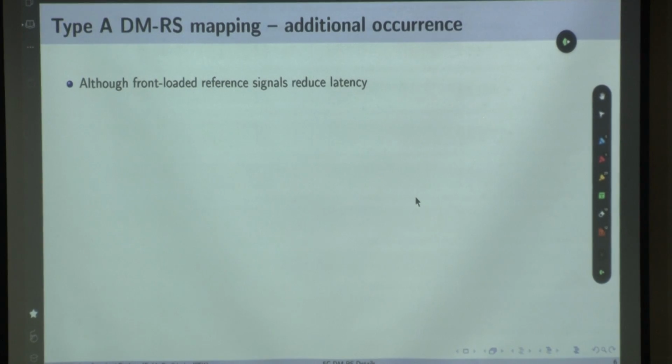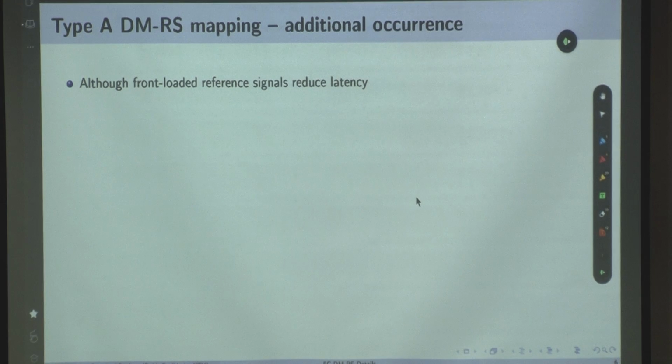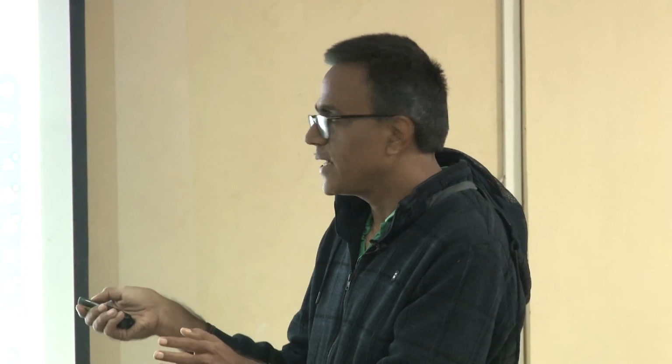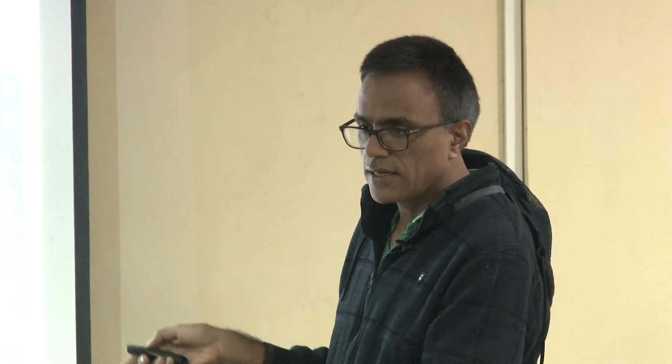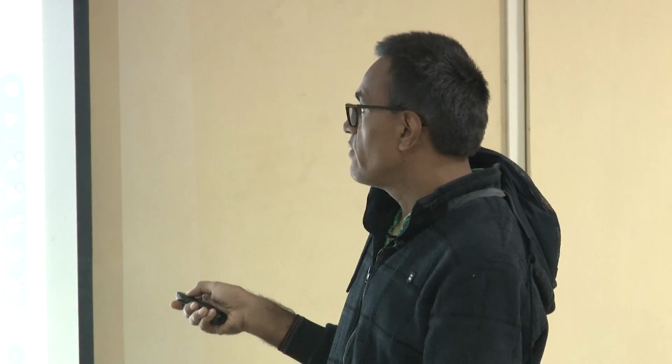Now, although these front loaded reference signals reduce the latency, since they come in the beginning of the PDSCH transmission, whether it was a single symbol or double symbol, and we know the objective is to reduce the latency, they may not be sufficiently dense in the time domain in the case of rapid channel variations.